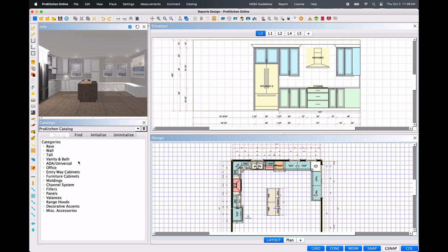Move the mouse into the desired view panel. This tool requires a point-to-point placement. A purple X will display at a corner point, and a purple circle will display at a center point. Left-click the desired point to start the dimension. Then drag the mouse horizontally to another point, and left-click to secure the dimension line. The dimension will place accordingly to where it was drawn.